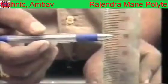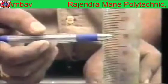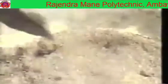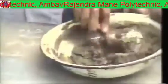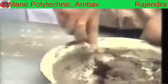Add water to the mix. The quantity of water to be added will be P by 4 plus 3% of the combined weight of cement and sand, where P is the percentage of water required for normal consistency. Mix it thoroughly to get a uniform paste.